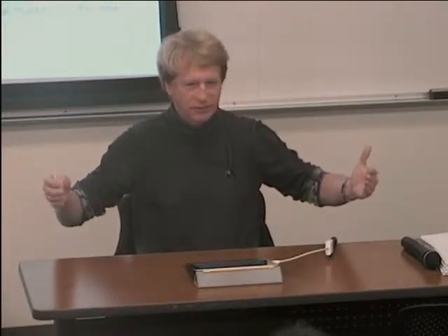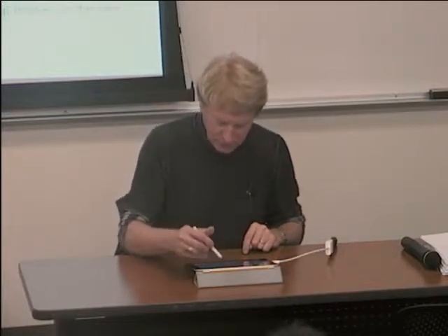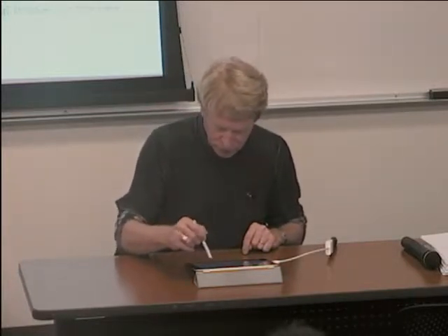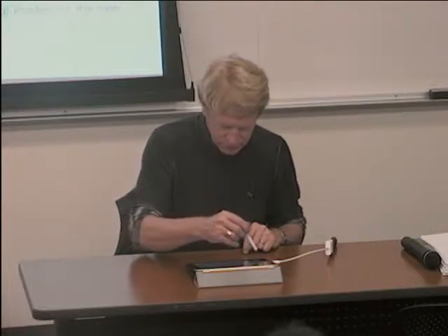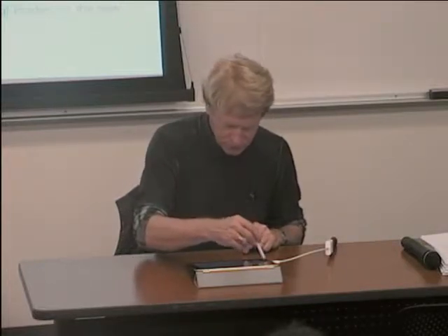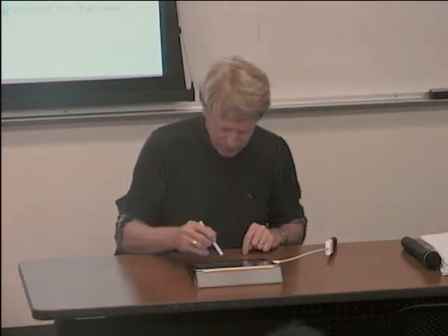Part two, the goal there was to say that now what we're going to do is just change the wafer size. We have a new fab. Instead of using 20 centimeter wafers, we use 30 centimeter wafers. For the rest, I can reuse everything. I can reuse the masks, and there's no design cost because I don't change the design. So NRE, in this case, is going to be equal to, let me just go back here. Okay. The NRE in this case is 0.